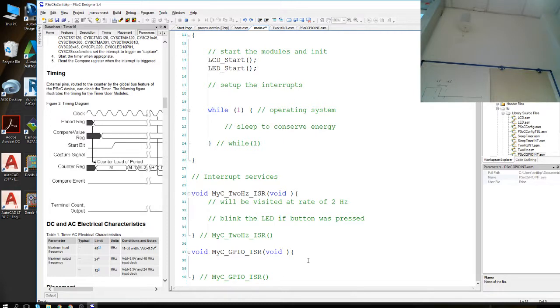Basically, this routine just sets a flag: now I have been pressed, do something. That's the correct way of using interrupt service routines in any case. Do as little as possible in those routines. If there are calculations which take time, and any arithmetic operation will take more time than simple operations, then you would just have flags here telling the other parts of the program to go on and do whatever has to be done.